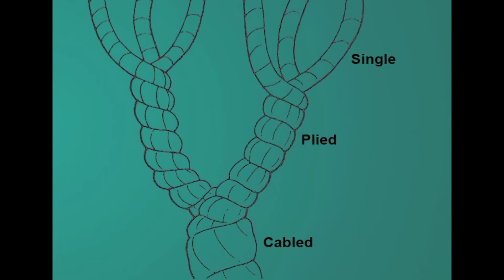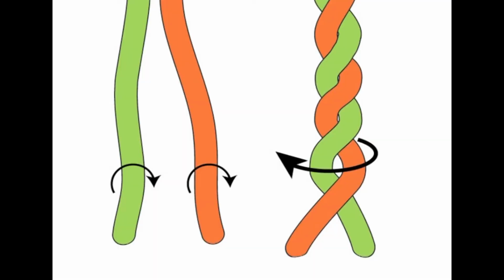So, in single yarn the fibers are twisted together, in a ply yarn 2 yarns are twisted together, that is 2 singles are twisted together to get a ply yarn, and from ply yarn the different ply yarns can be twisted to get a cable yarn depending upon the usage and depending upon the end use of that. And in case of double yarns, 2 single yarns which have an identical twist will be twisted together in the direction which is opposite to the single yarns.